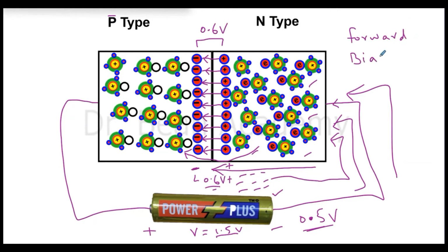When you connect the p-type side with the positive terminal of the battery and the n-type side with the negative terminal of the battery, the PN junction is in forward bias mode, and in this case you will see the flow of current as long as the voltage of the battery is greater than the voltage of the potential barrier. Silicon is the commonly used material for PN diodes, but there may be other materials, for example germanium.